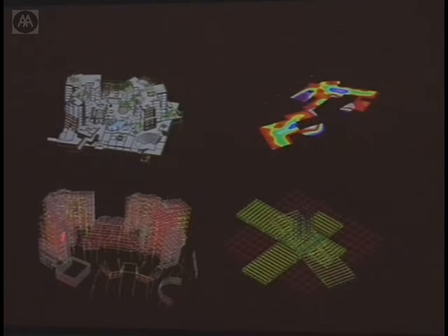As you know full well, you can take these models and use them to do all kinds of engineering analysis, whether it's thermal analysis or structural finite element analysis. This one here is actually research into a very particular difficult joint in concrete. These are all rebars, and you can see the mesh for the slab. And these are the framing beams in the slabs. And then you've got some sort of column coming down into this diagonally jointed thing. The only way to work out whether this column really worked was actually to detail the rebar in 3D.